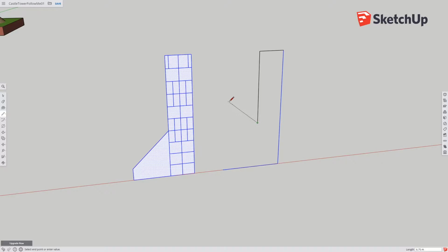and I'm following the red axis. You might be drawing on the green, like that. Okay, but don't draw without it being the red axis or either the green one. They're perpendicular to each other, but I'm working along that red axis there. I want to come down here, but I don't know where to stop. So what I'm going to do is hit escape, pencil tool from that in there, and come up whatever that was there, 1 meter. Come up the blue.